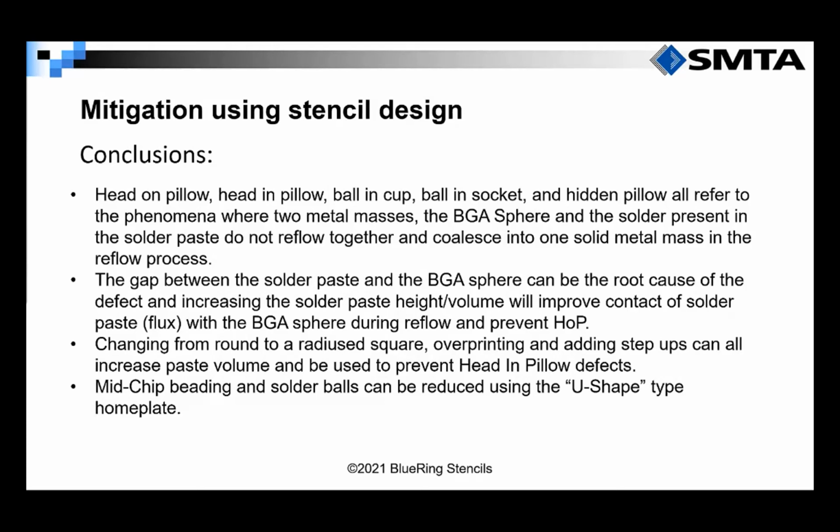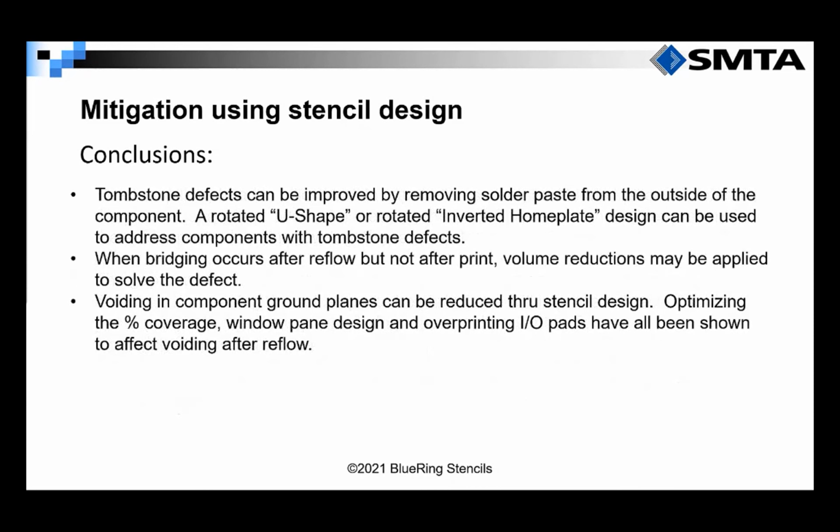Then we addressed mid-chip beading and discussed removing paste from the inside center of the pads and how that could reduce solder balls or mid-chip beading on the stencil design, especially when no clean pastes were being used. Finally, we talked about tombstone defects and how they could be improved by removing solder paste from the outside of the component.